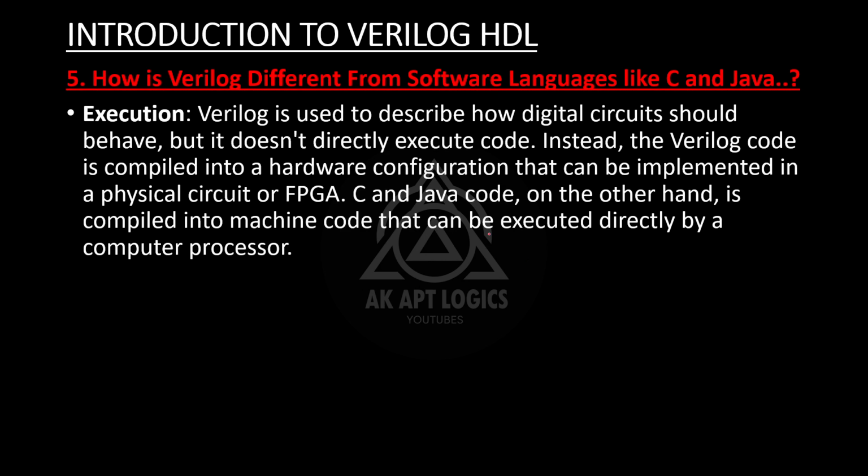Execution. Verilog is used to describe how digital circuits should behave. This is the thing I have discussed, right? But it doesn't directly execute code. We are not executing the code. We are just applying the test cases to check whether the design is correct or not. We will check it and we'll get some waveforms.